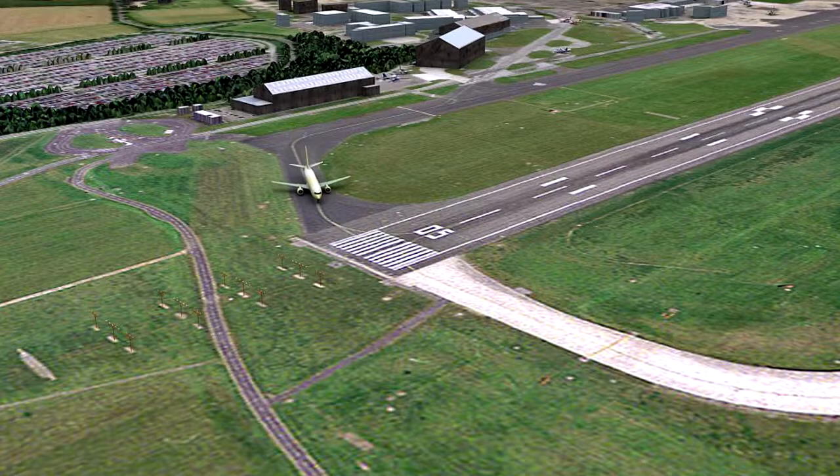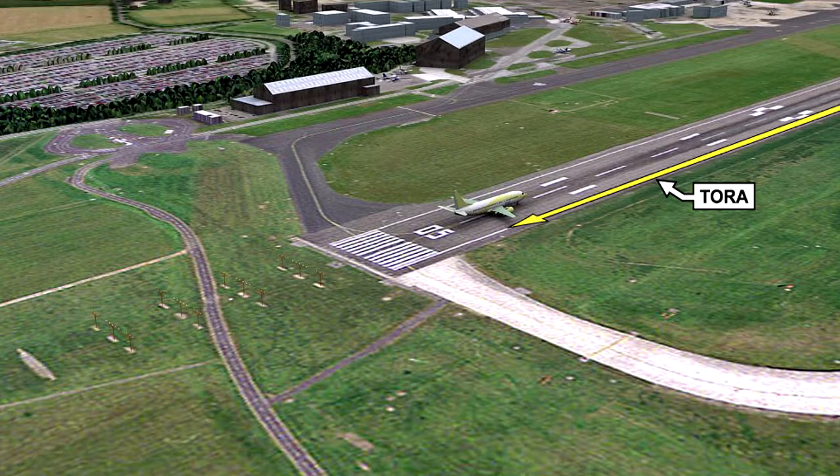For instance, large aeroplanes will use a portion of the runway to turn and line up ready for takeoff. As such, the start point of the takeoff will be some distance in from the edge of the pavement. Due account of this must be made by the pilot. In such cases, the actual takeoff run available will, of course, be less than the paved runway length and the distance between the thresholds. This type of takeoff run available reduction is published in the aeroplane flight manual and not in the aerodrome information documents.